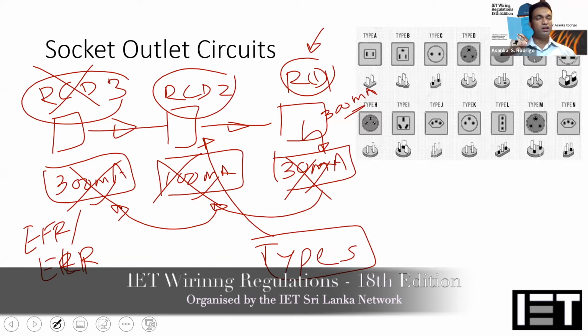That's why I said, if you are designing a TT system, you have to have a separate electrode for the transformer neutral and the generator earth. There is no problem with connecting the generator neutral and the transformer neutral together, because they are not running in a synchronous manner: if the transformer is not available and the supply is not available, then only the generator runs. But for the electrical installation, if you are maintaining a separate earth, they should be separated by at least something like 20 meters. There is a thumb rule that can change from location to location. As a thumb rule, you had better maintain at least 20 meters of separation from those neutral points to the installation. As I said, the concept is okay within the installation.